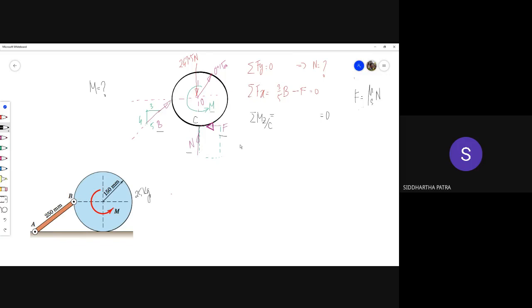Okay. Earlier, when we knew that there was not going to be any relative motion, like a general equilibrium problem, where a frictional support was as good as a pin joint, there I didn't have to know the direction of the friction force. But this time, when I'm about to have a relative motion, then I need to know the direction of the friction force.